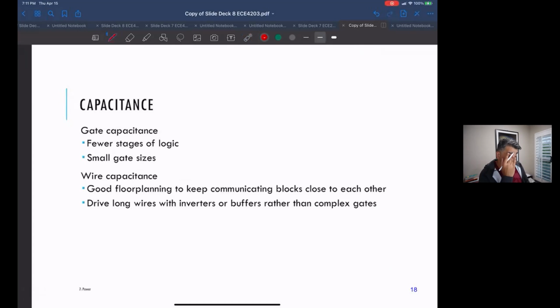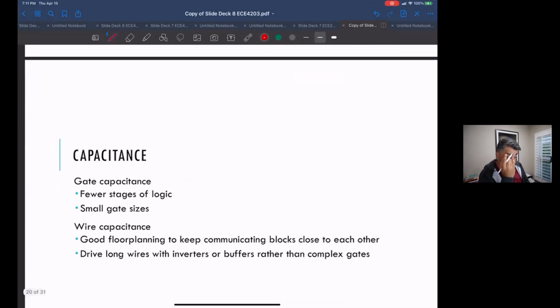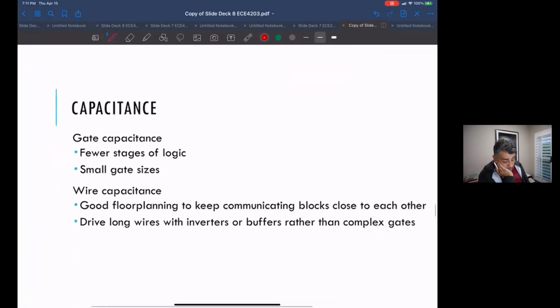So that's an option, although usually the benefits of something like this are a lot less than clock gating. It's a lot of work to optimize your layout. I think you always want to optimize your layout while you're doing it, but after the fact, it ends up being pretty difficult to get big benefits.